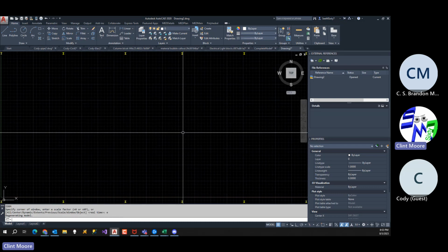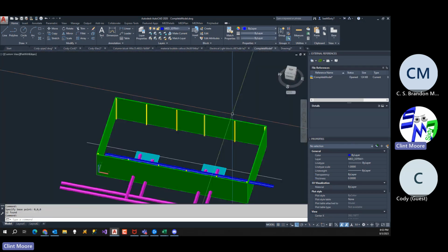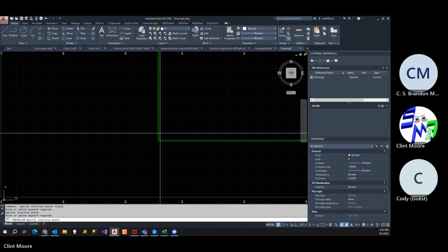Now this is my structural steel model. I might want to go ahead and include the building with this, okay? But I might not. But since this is a building, I am going to include that. So I'm going to go back over here. I'm going to Control Shift C from 0,0, and I'm going to go ahead and pick my building as well. That's all I want in this model. Okay, Control V, 0,0, boom. Now, does it make sense?